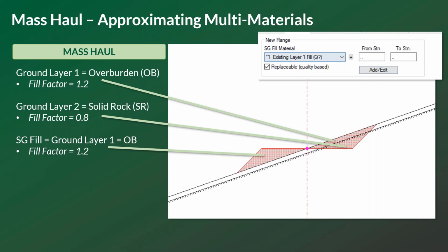Now let's put a little bit of numbers to the geometry here. So we'll start through that unfactored lens. So overburden cut, 4.75 cubic meters, and I'll say cubic meters, just a little more intuitive to talk volumes than something infinitely thin. So solid rock cut, we've got 4.95, and our total cut is 9.7.